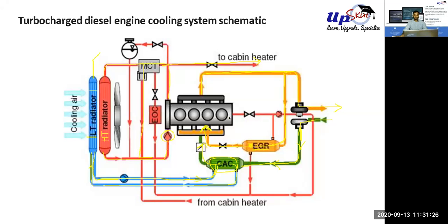So what we are doing is having coolant go through this exhaust gas cooler, or the EGR cooler, and it will eventually go to the radiator. We also sometimes need cooling for the turbochargers. Some kinds of turbochargers need cooling, and water will pass between their shells, at least on the turbine side. Cheaper turbos don't have cooling, and they sometimes become red hot after running. So yeah, lots of elements are being added here.